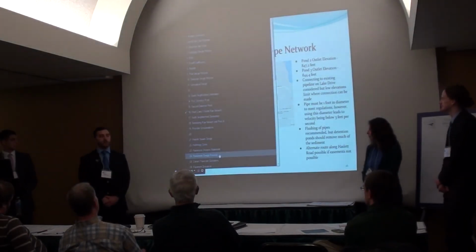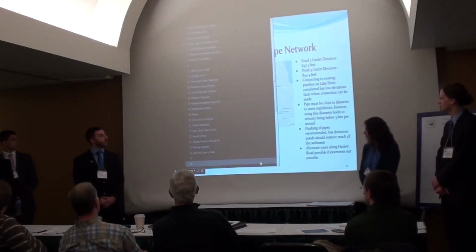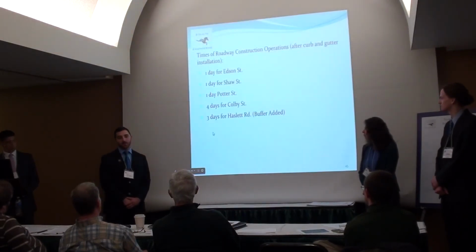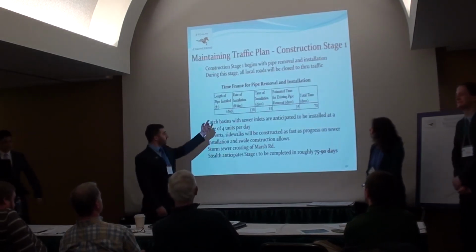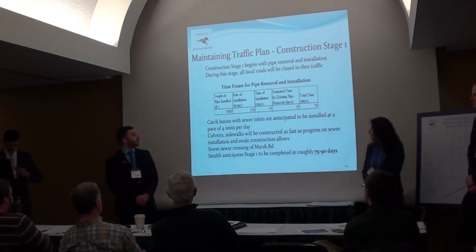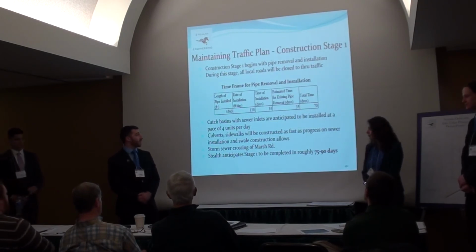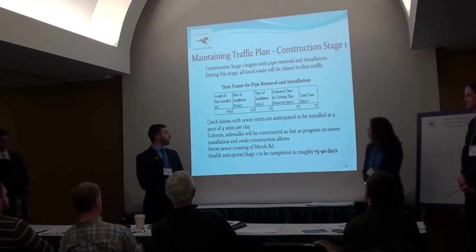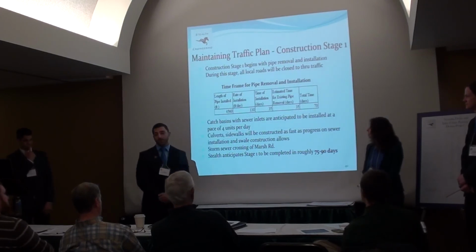You have X amount of days for pipe installation, X amount of days for paving, etc. I've got roadway design that gave a rate for installation based on the size of the pipe that we're using and the type of environment that it's being installed into, and just took the linear feet that was being installed within the neighborhood, divided into the estimate for installation.